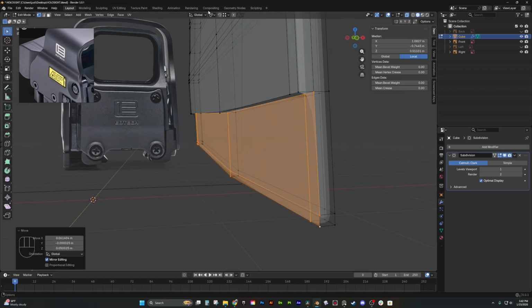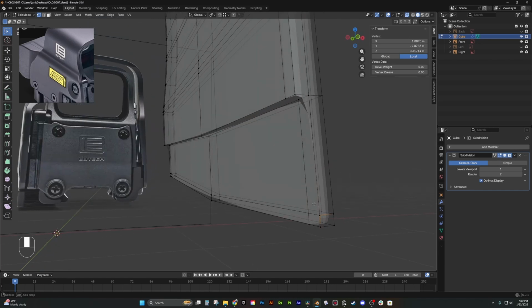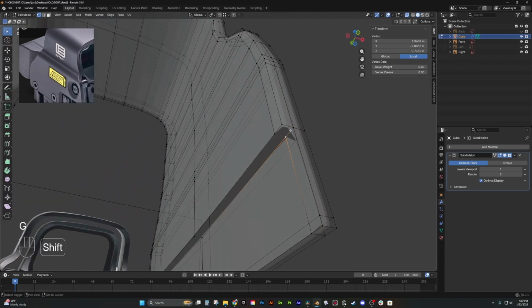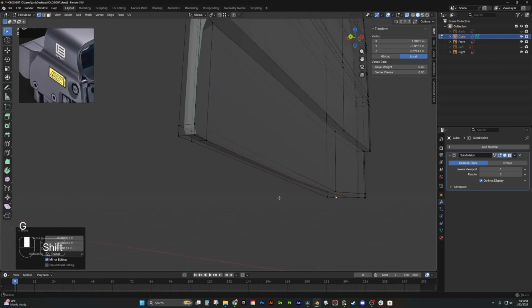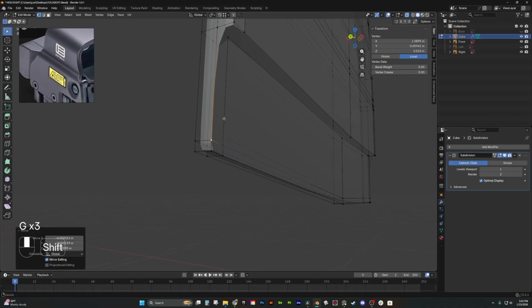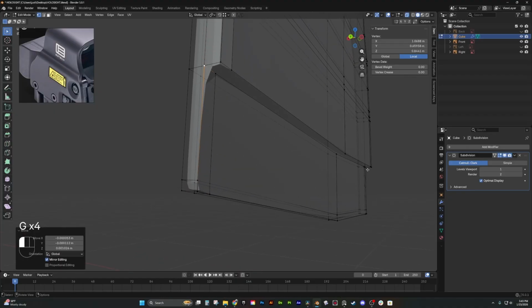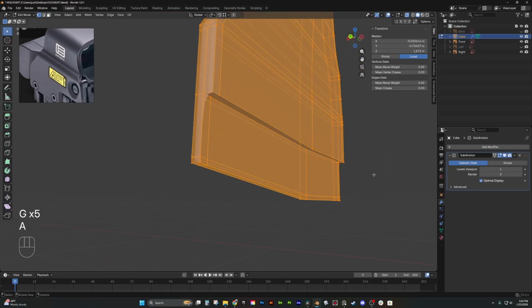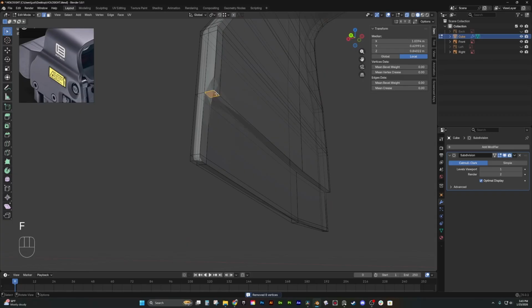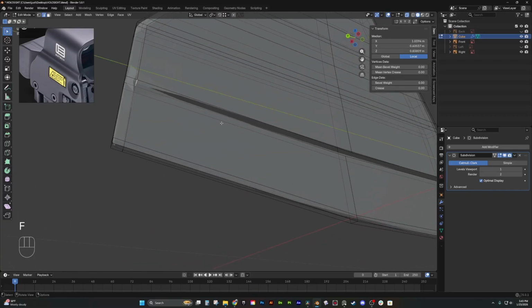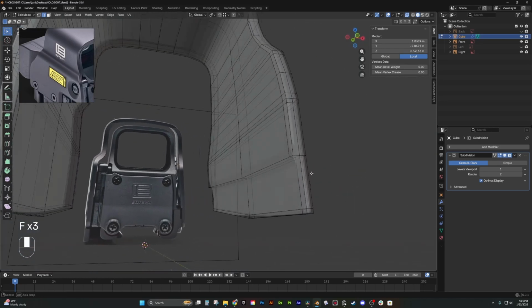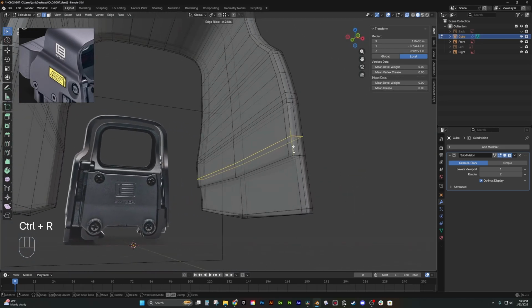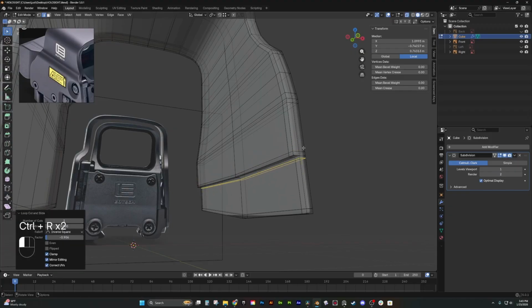However, we are going to turn on vertex snapping and make sure that all of these are snapped in the right location. So I just moved a vertex, held Control. I'm just making sure that these are all in a decent spot where they would be merged. I don't have auto merge on, and I'll merge them by distance. Right about now, actually, I'll press A, M, and then merge by distance. Now I can take my edge tool and grab in between these and press F. And with that F2 add-on, I can press F again, and F again, and it just completed that whole edge loop for us. We can even add a new control loop with Control R, and we just tightened that edge as well.